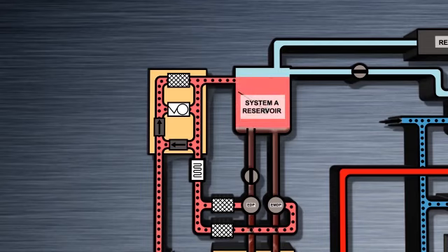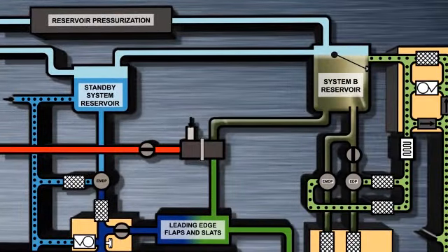At this point, the hydraulic fluid quantity indication on the system's display will read 20%. The remaining fluid in the reservoir will be sufficient for the electric pump to continue operating. If a leak develops in the electric pump or its related lines, the entire reservoir will drain and the fluid quantity will read 0%.